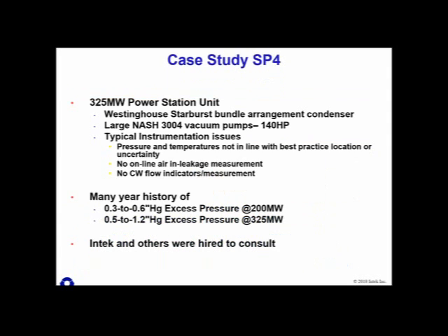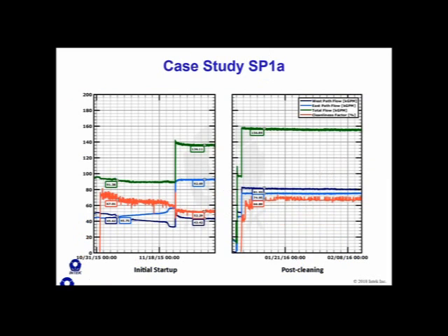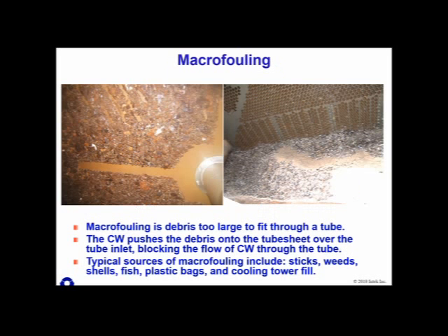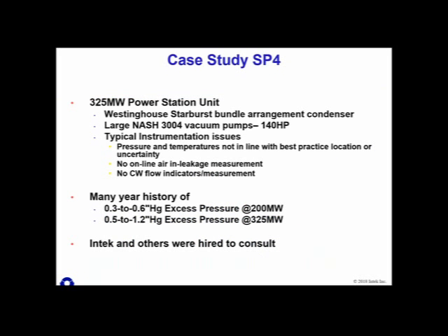So the one thing that I want to point out here is that this problem, and I thought I had it in the slide, but in addition to the excess back pressure that I talked about at the beginning of the slide, this was an additional 6 or 7 tenths excess back pressure at high load. I think 3 tenths at low load. This right here, if undetected, is a $500,000 problem per year. So if they had not detected this, this is a big problem. So that's the value of the problem that we found here.